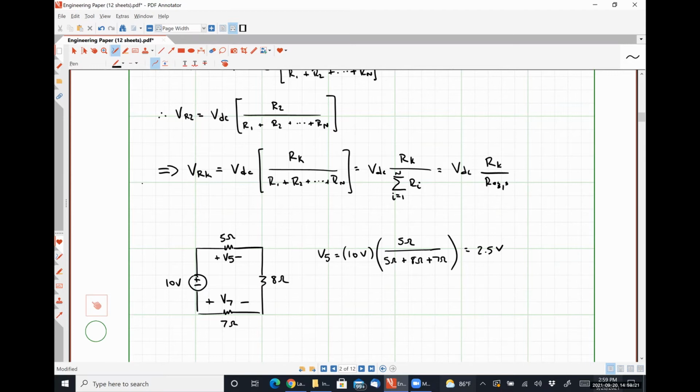Another way to think of it is that as we defined our current I, that current I is now flowing into the negative polarity terminal. So when we calculate that voltage, we put a negative sign, okay? So nothing wild or crazy here, but it is something that will potentially trip you up and cause you headaches. So if you ever are doing voltage division and you want the voltage with the opposite polarity as what you would expect, simply change the sign on the voltage. It's that simple.